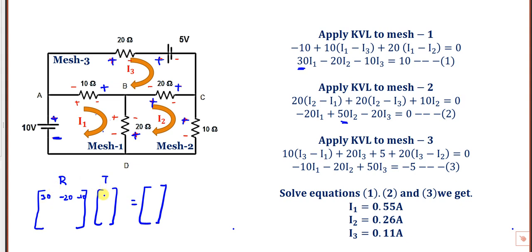And after that, first you write the three unknown variables, the currents: I1, I2, I3 are the currents. And in mesh 1, in the clockwise direction, we get first minus to plus. So while writing KVL, please see here, first we got minus 10. If you bring it to the right side, it becomes positive. While writing KVL, minus to plus means minus 10 on the left side; after bringing it to the right side, it becomes plus. So that is equation number 1.